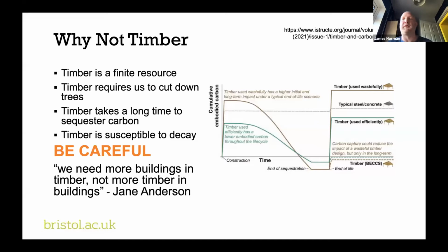There is a danger to think, well, the more timber I put in my building, the better, because it will sequester more carbon. But this is not holistic thinking. That works maybe for your project, but as soon as we think about the entire timber system, that is a broken way of thinking, because actually it reduces the number of projects we can build out of timber, which is why we need to be building more buildings in timber, not more timber in buildings.